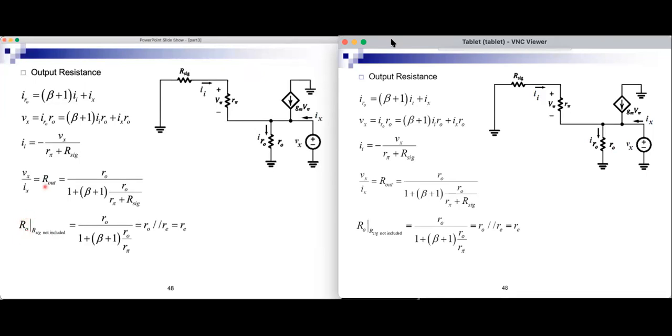And another one, an R out, which is not really the output resistance of the amplifier, but sometimes we need to calculate it, because if at the output I have a capacitor and I want to find the resistance seen by the capacitor when I'm doing OCTC, then I calculate this R out, not this RO. If I'm just calculating the output resistance of the amplifier, it's a simple RO, and the voltage here, VI, will be set to 0.